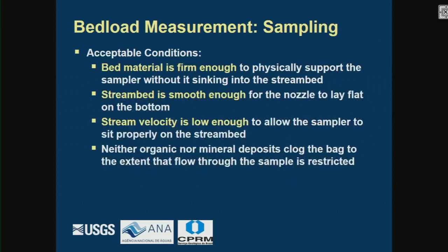So there are some things to consider as you think about lowering a sampler all the way to the bottom. One, you need sediments that are firm enough that the thing is not going to sink through. Think about maybe a really fine grain system, which you probably wouldn't be concerned about bed load anyway, but some of those bed sediments are really soft and the sampler would just sink into the bed. Another big thing is, is it smooth enough?